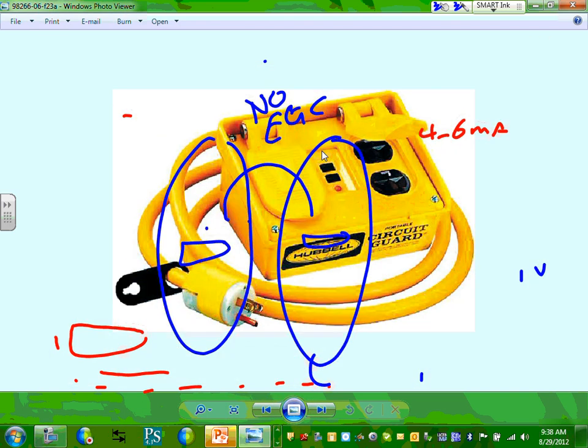So what is required: if I'm busting this wall right now, and I'm using this receptacle to drill a hole in this wall doing construction, I have to be plugged into GFCI. Or if I just want to use this permanently installed receptacle, I have to change it to GFCI, or I have to use a system like this, plug it in where you have GFCI protection. This is OSHA too. It's nothing new.